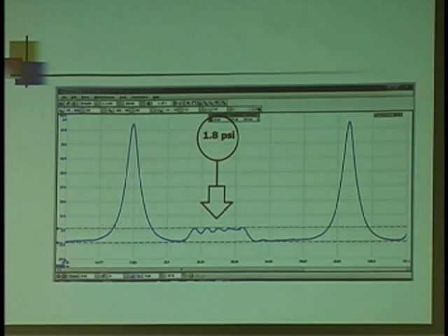Ideally you should do a snap throttle and watch that pressure plateau. If the exhaust is clogged, you're going to see it rise rapidly. What about the little squiggles? Do they mean anything to me? What's going on in the exhaust manifold? Turbulence of the air. There are other cylinders dumping in there, right? So that's what I'm seeing there. Same with those squiggles we saw on the first look sensor. There's more than one cylinder dumping at the same time.